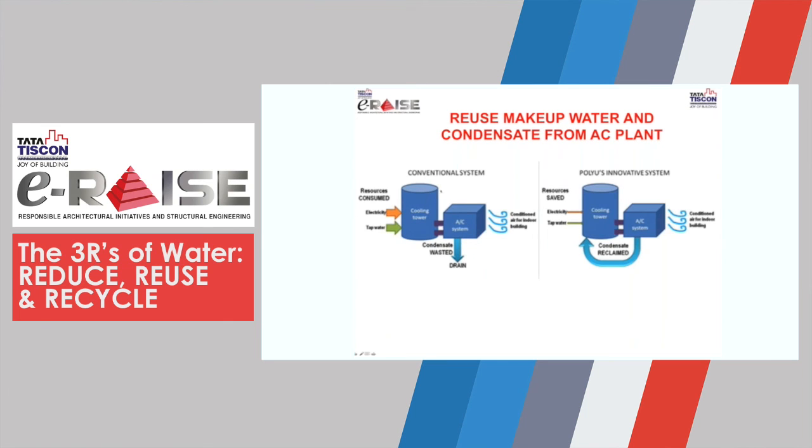water. So the need for AC, like I said, in hospitals, in hotels, in certain areas, AC is unavoidable. And what can we do under such a situation to reuse? What can we reuse? The condensate, because we are dehumidifying the air in an air conditioning system. There is a lot of condensation, and what happens to that condensate? It is completely wasted. Now, the concept is to reuse that condensate for the makeup water of the cooling tower. As I'm talking, I'm getting some condensate on my arms, and I'm wondering how did this magic happen?